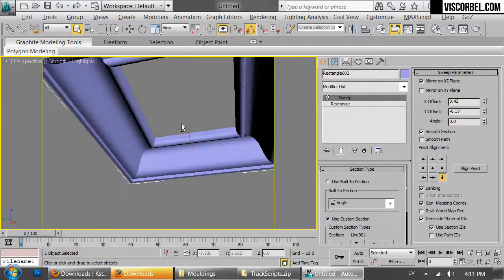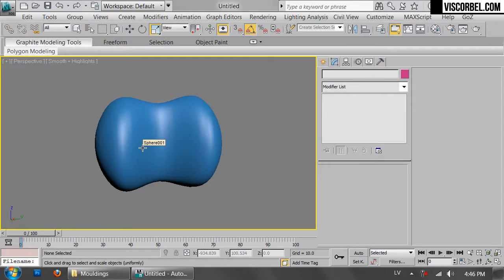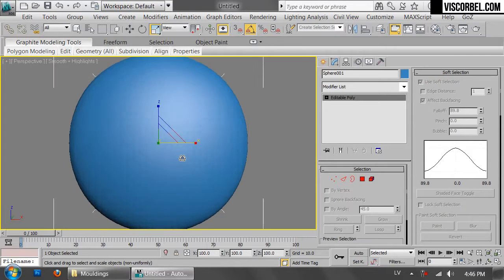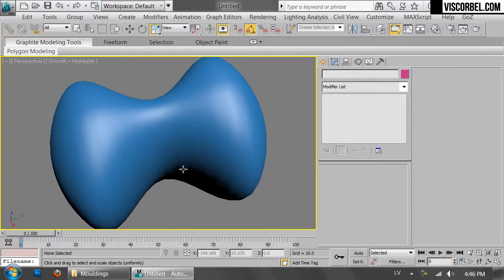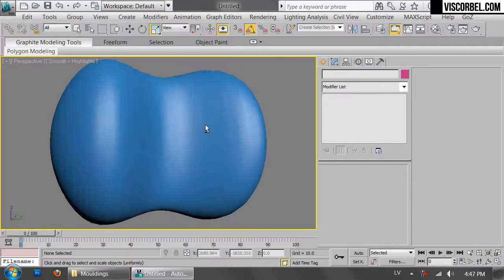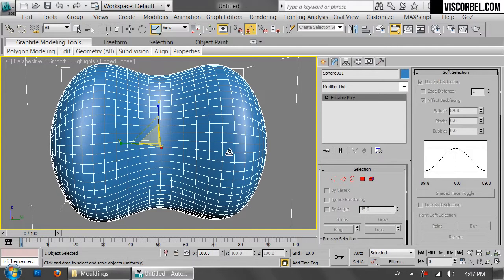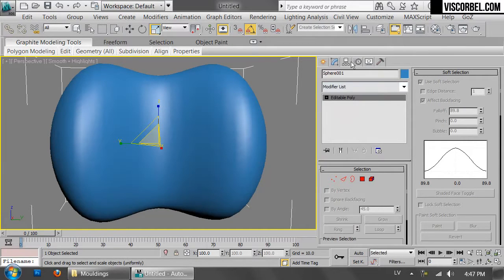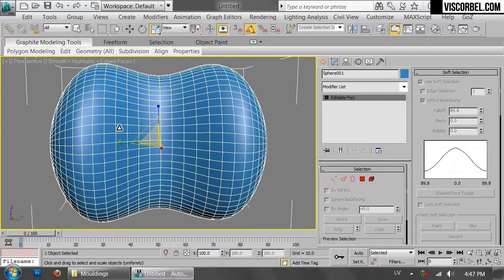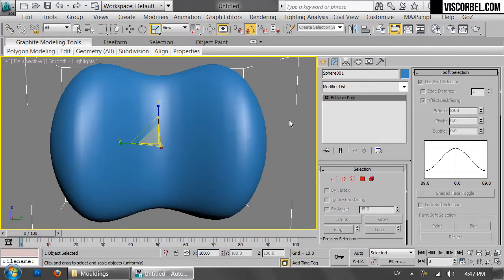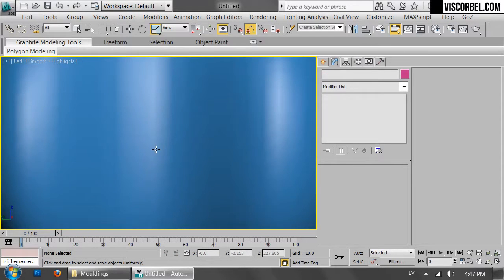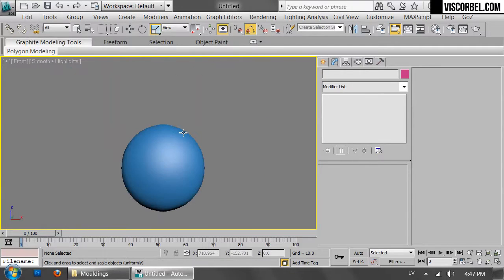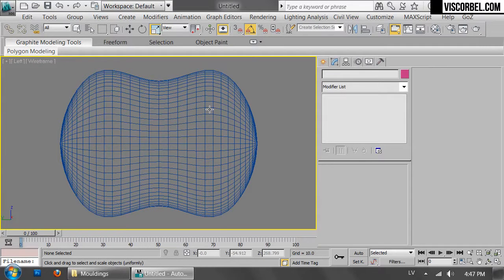So these are the basic ways to create some moldings. There are some cases when it's only viable to create the molding manually. For example, when you have to conform it to a difficult object like this one, where the surface curves in multiple directions. And in these cases it's quite difficult to use any modifiers to distort your profile correctly, or you can't really conform a spline to this object and use the sweep modifier or bevel profile modifier, as they do not work correctly in these cases.